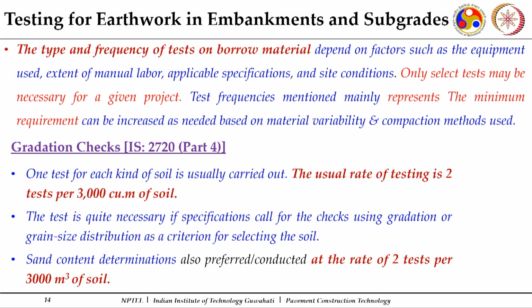Now, the requirement will come up: how many tests do I need to do? Should it be in terms of the area, or in terms of the quantity, the volume of the soil which is going to be used? So, how many tests are to be done in a given volume of soil? The frequency is important: how many tests and how many times it has to be done.